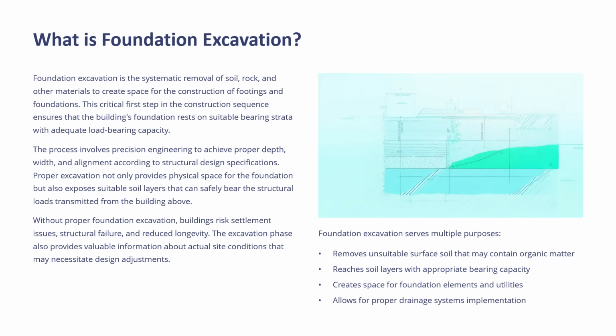Proper excavation not only provides physical space for the foundation but also exposes suitable soil layers that can safely bear the structural loads transmitted from the building above the foundation. Without proper foundation excavation, buildings risk settlement issues, structural failures, and reduced longevity. The excavation phase also provides valuable information about the actual site conditions that may necessitate design adjustments.